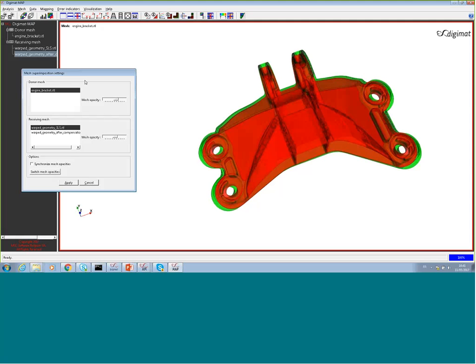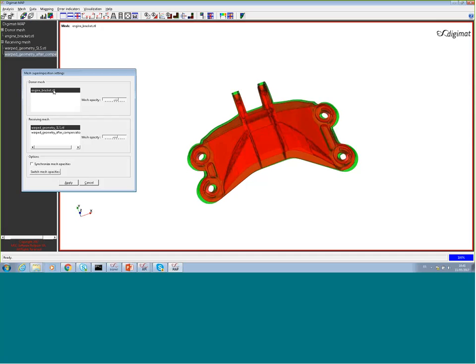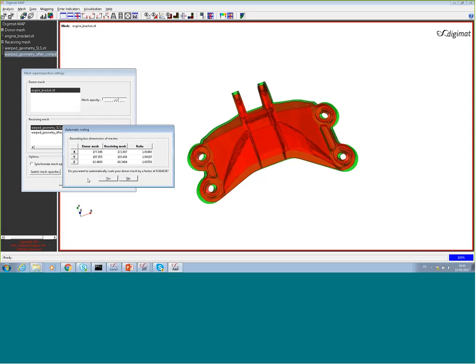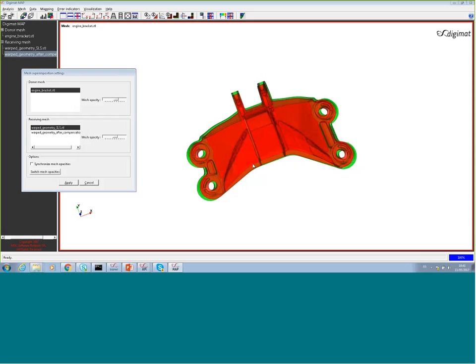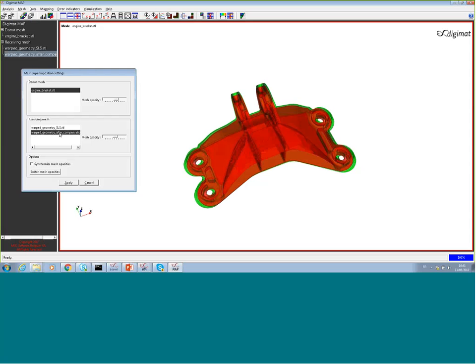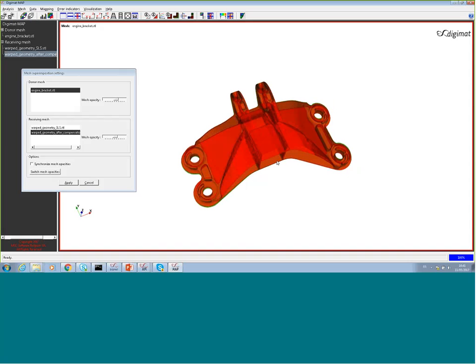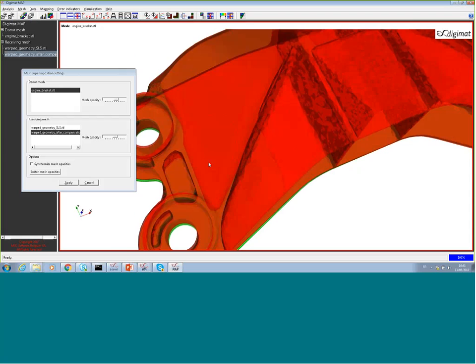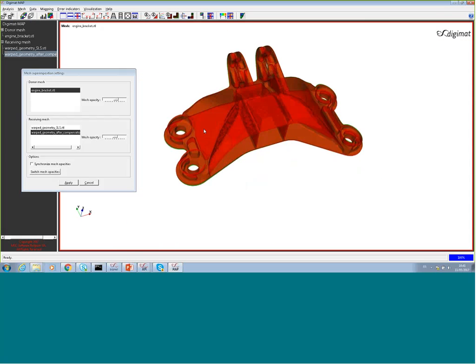And so just to compare also the geometry, the warp geometry after compensation, so the one we are looking at here in the second step, you can see that we go from this configuration, okay, where we have obviously not the right geometry, to a warp geometry, so a printed geometry, which is here in red. Okay, so very nice improvement. You can see it's still not perfect, so there might still be one or two iterations that need to be performed, but it's improving a lot the warpage that we get.